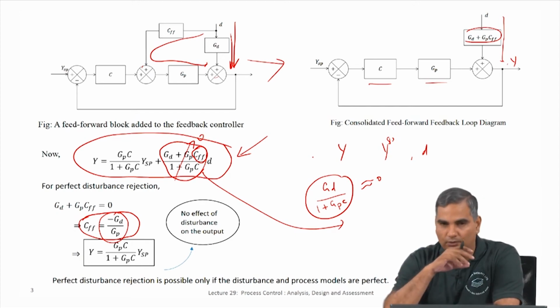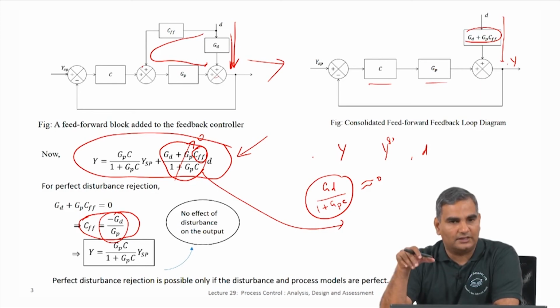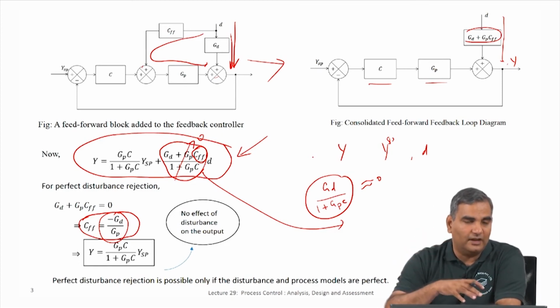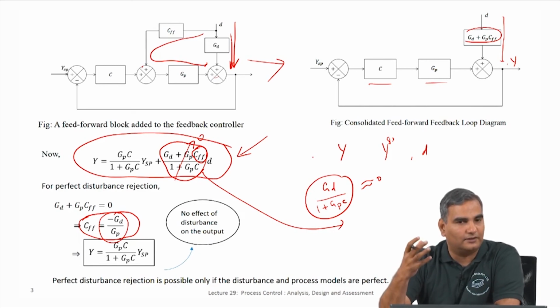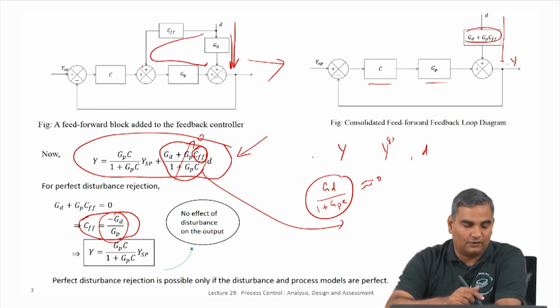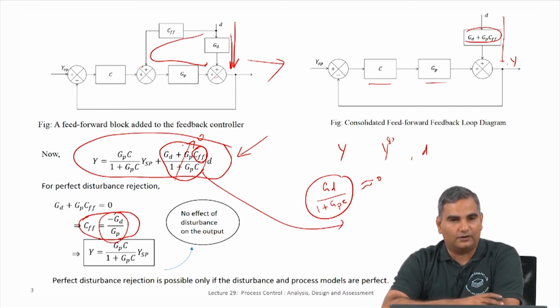If you think of two loops U1, U2, Y1, Y2, whenever you change U1, Y2 also changes. So, you can think of U1 as a disturbance for Y1, and similarly you can think of U2 as a disturbance for Y2. Is there some way in which we can do good control while rejecting the disturbance effects that come from the other loop? If you think of what is happening in the other loop as introducing disturbances in this loop, is there some way in which I can nullify that effect using very similar ideas in terms of setting some transfer functions to 0?